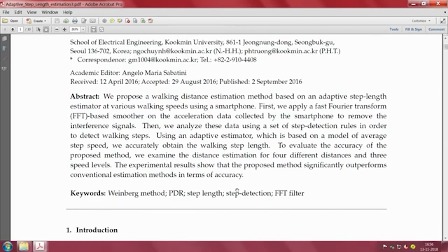I mentioned to you in one of the previous slides about getting raw accelerometer data and then applying a filter, right. Now we could be applying, as I said, different orders of filters. One of them which is quite popular is indeed the Butterworth filter. Here in this paper they do it differently. What they do is an FFT and then an inverse FFT back, and that is purely for the purposes of noise removal. So we will see those results also. So you can also apply FFT and inverse FFT to smoothen the raw values that you get.